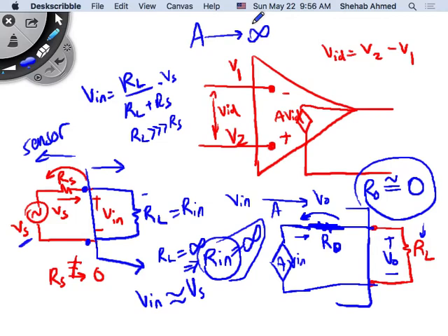Of course, it would be great if I could design op-amps with any gain I would like. It would be great to design an op-amp with a gain of 1, 2, 3, 4, 5, 6. But that becomes ridiculous because you cannot manufacture all of these different kinds of op-amps. But the way it is now, with A equal to a very large gain, allows us to put some circuitry around it to control the closed loop gain. So A is here the open loop gain, meaning the op-amp operating by itself, nothing around it. Only the input signals V1 and V2, and I measure the output.